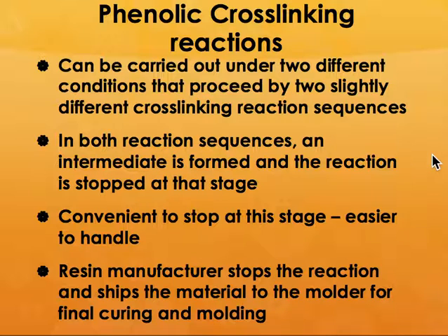So these types of resins are called B-staged resins. And that's what you will find available in the marketplace. And the resin manufacturer will stop this reaction, and he or she will ship the material to you for the final curing and molding.